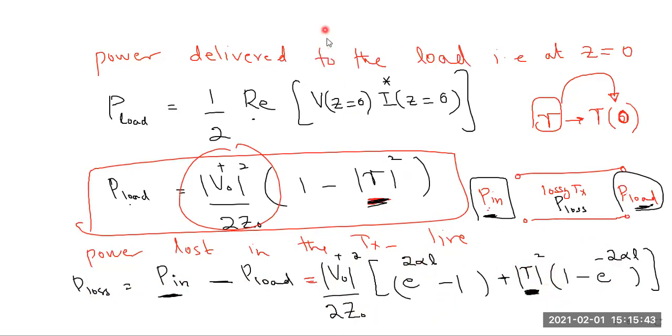On a transmission line, some power is going in this direction and some power is going in this direction after reflection from the load. So on this lossy line, there are two waves traveling, one from left to right and another from right to left.